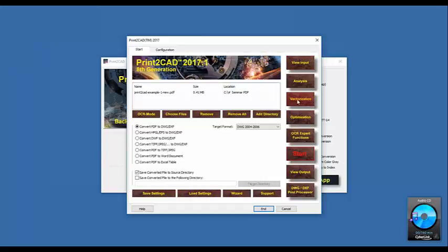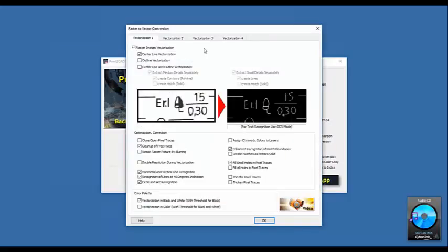Now I start the vectorization. And here I decide what kind of vectorization I want to do. And Mike, in the drawing you sent me, everything you do is only to take care of this vectorization, nothing more, because your drawing is only a raster picture. And here I decide I make a center line vectorization.